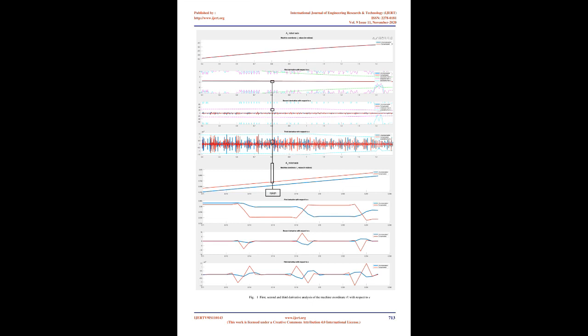Equation 10 determines an array of values for the ith machine coordinate, i equals 1, 2, 3, 4, 5, 6, for each of 2,900 values of total vector displacement s of the robot axes. Numerical procedures for approximation of the first, second, and third derivative with respect to the total vector displacement s are applied. These derivatives are denoted as follows. This way, vectors containing the first, second, and third derivative of the 6 robot axis positions with respect to total vector displacement s are obtained. Derivation of equation 21, as well as acceleration and jerk constraints derivation details, could be found in 6.